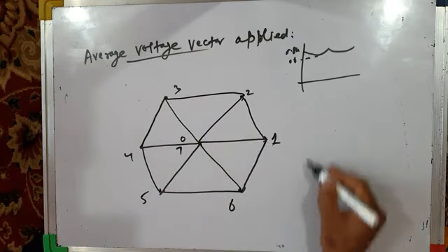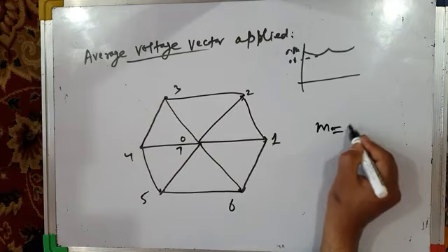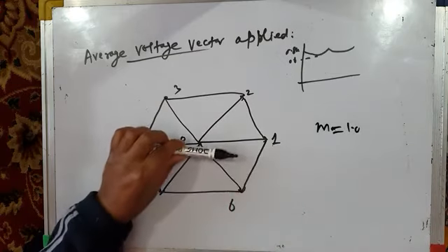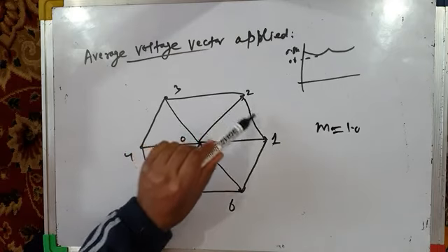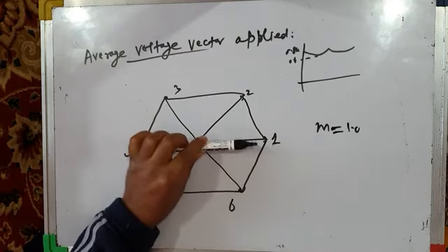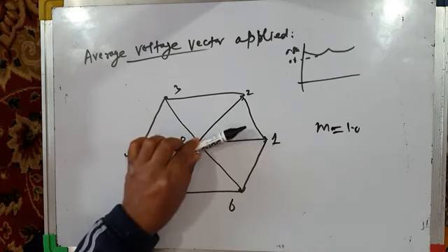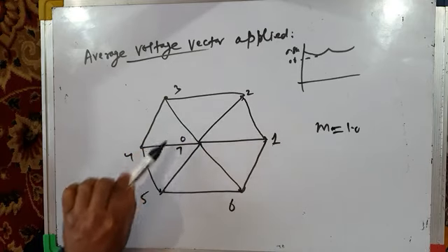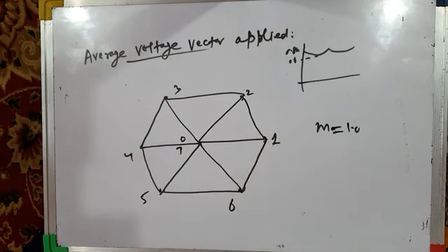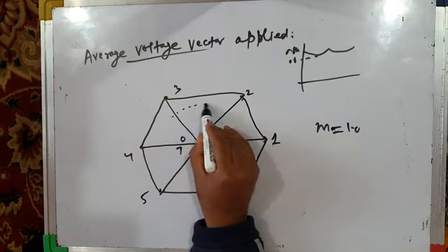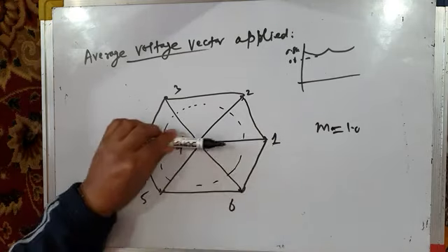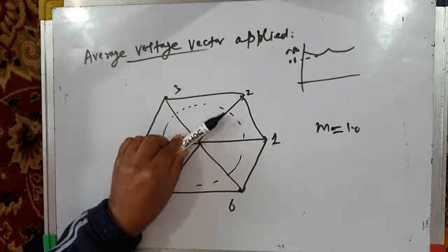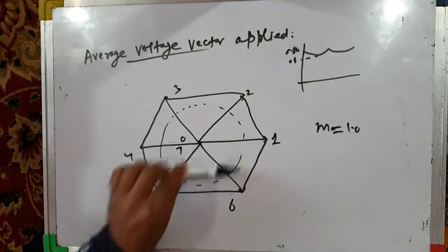For under modulation and up to a modulation of m equal to 1, your rotating reference vector, when it is sampled in a particular sector by time averaging of 3 vectors, moves with each sample and traces a circular path, and its amplitude is constant. Constant amplitude means it moves in a circular trajectory. It moves linearly like this, traces this circular path, and magnitude remains constant.